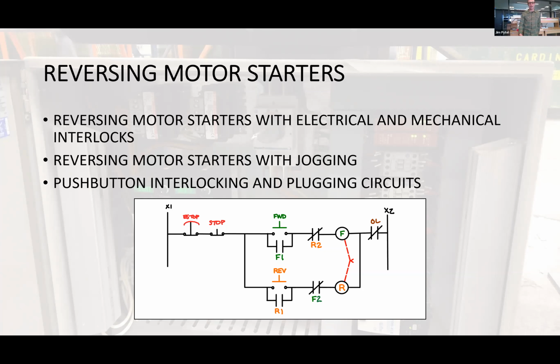Now they've got some good wiring practices. They understand wiring numbers. They're capable of working with their partners, and I just let it run. Super important about this, which I should have mentioned earlier, part of that kit includes a locking plug cover. Obviously, in a lockout/tagout environment, with two students working together, they each have their own keys. In an industrial environment, don't do that. Have one set of keys, and you have the keys. It's very important to keep the students from plugging it in. Before you plug it in, you verify it and you unlock it.